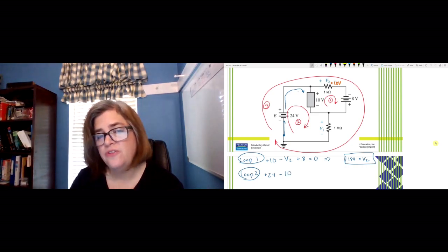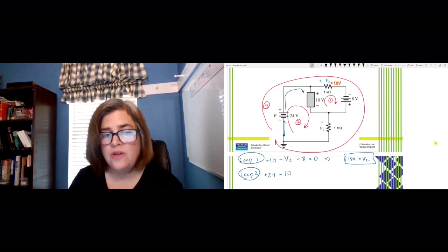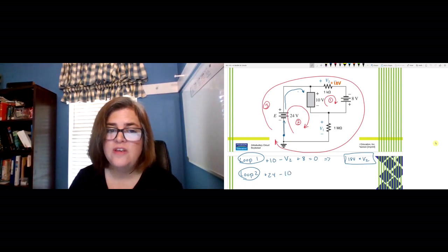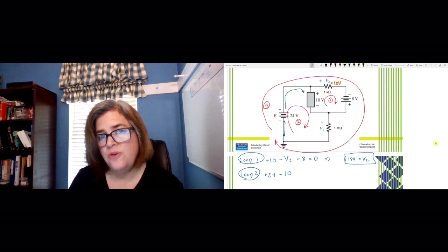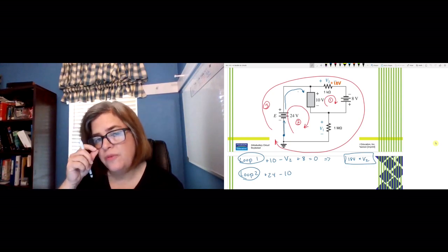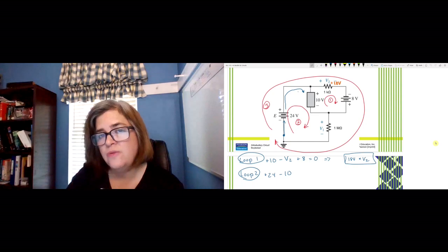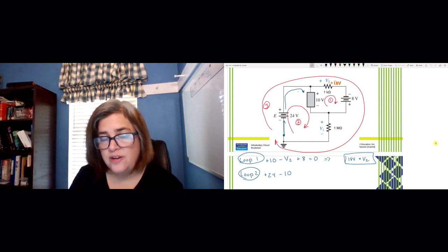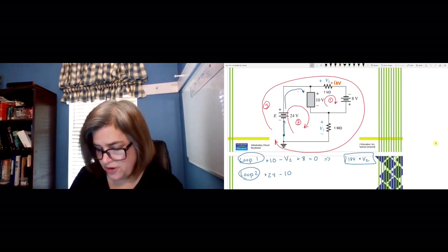So it doesn't matter if it's a source or a resistor, because we care about the direction of that voltage, not necessarily what it is. So you can't just add all of the sources. Some of them may be going in the opposite direction of the original source. You'd have to subtract it then. So you have to pay attention to the direction.